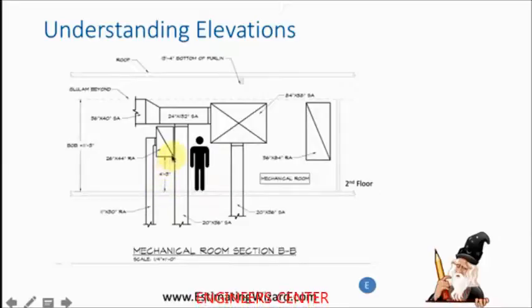and this duct is 4'3" from the floor to the bottom of the duct. And this is BOB, meaning bottom of beam, is 11'3" from the floor to the bottom of this big glulam. So this big wood beam here, it's 11'3" to the bottom. And here you are standing in there. So basically, this is a cut of the building. It's considered a section. So this is an elevation. This is a section view. Same thing.